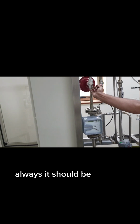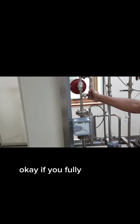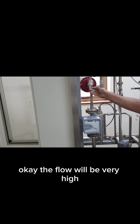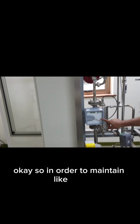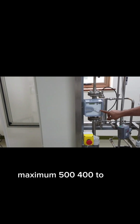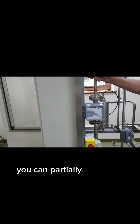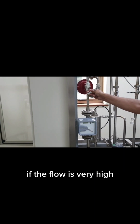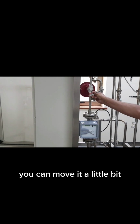Partially. It should always be partially open. If you fully open it, then it will be very high flow. The pump flow will be very high. So in order to maintain 400 to 500, maximum 500, you can partially pull it out and play with this. If the flow is very high, you can move it a little bit.